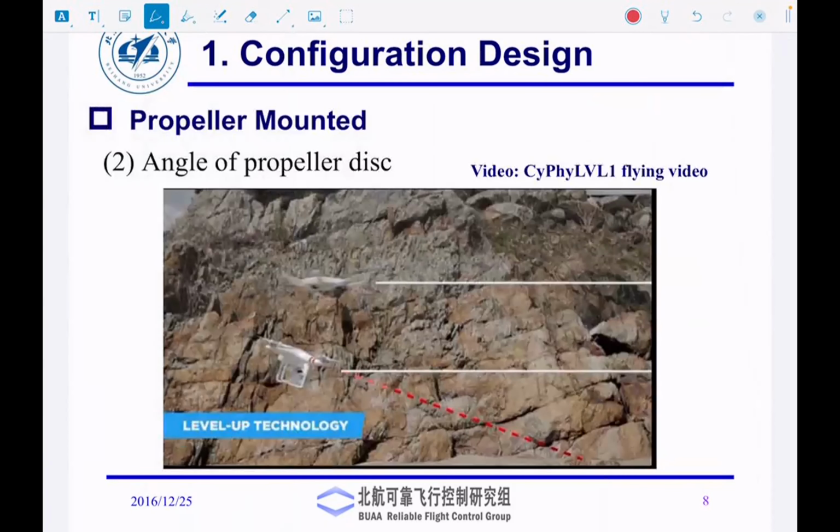Now, again, we just talked about it. Again, this is the DJI drone. So the application of the DJI drone is for camera stabilization. There are different techniques for stabilizing a camera. One is digital stabilization, which means you have an IMU inside, and that IMU, based on the orientation and vibration, will run a built-in filter that will take out the jitter. So basically that is the gimbal-less camera. Or you could have a gimbal, and basically you would have motors that would stabilize the camera in a particular location.